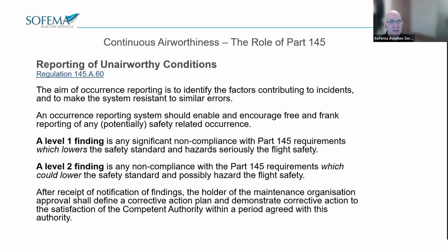So what does endanger flight safety mean? It means any instances where safe operation could not be assured or which could lead to an unsafe condition. They might include, but not limited to, significant cracking of structure, deformation, corrosion or failure of the structure, any evidence of burning, electrical arcing, significant hydraulic fluid or fuel leakage, and any emergency system or total system failure. These normally would not be in existence at the time you certify the aircraft for release of service, but they might happen in between and perhaps be discovered during line maintenance.